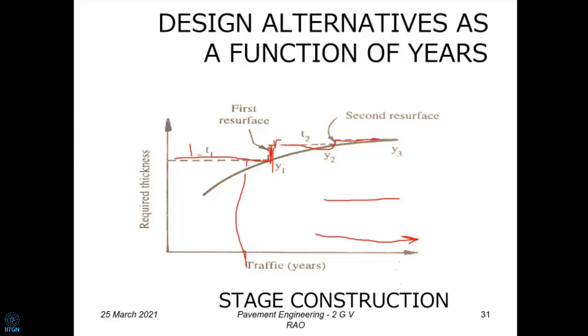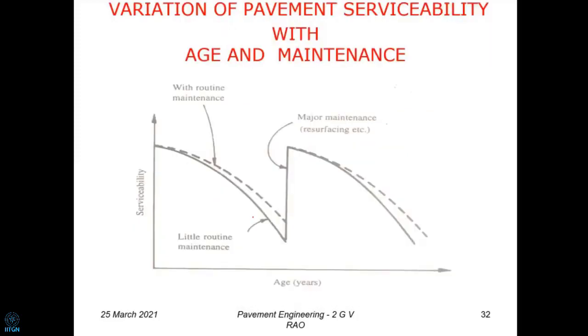So this is a policy which you are going to think: no, I am not going to run this road for the next 5 years. That could be one thing. Other people say that, okay, every 2 years, 3 years, we are going to improve the surface and things like that. Road condition is going to be all right, and less water is going to come into it. So the question is, is it almost annual maintenance, and every 5 years or 10 years is going to be major maintenance. Okay, so this is what we call the pavement management system, which is a function of time. Of course, in that time we are going to say this is the number of movements and number of axles that are going to travel, and then you take a call on how you want to design actually. The same thing we are going to do in terms of age.